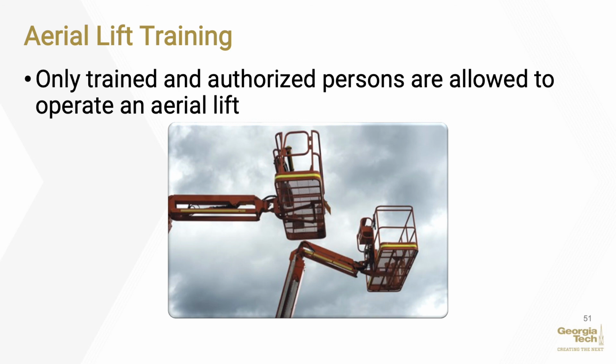Training should include explanations of electrical, fall, and falling object hazards, procedures for dealing with hazards, recognizing and avoiding unsafe conditions in the work setting, instructions for correct operation of the lift, including maximum intended load and load capacity, demonstrations of the skills and knowledge needed to operate an aerial lift before operating it on the job, when and how to perform inspections, and manufacturer's requirements.